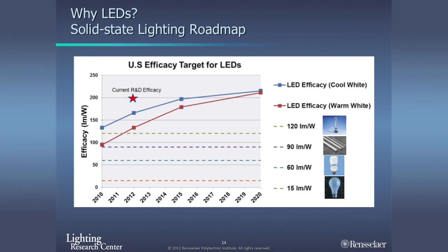They are typically more efficient because they rely more on the LED and less on the phosphor. So those are up almost to 200 lumens per watt by now, and then we see the warm whites a little bit under that, about 160 to 180 lumens per watt. But still, from an efficacy standpoint, that's much better than existing sources. By 2016 or so, we will see them cross the 200 lumens per watt mark, which makes it twice as efficient. So imagine that if you have fluorescent lighting in your building and you were to replace it all with the very highest quality LEDs, you could potentially cut the cost of that by 50%. And that's huge. Never before have we had a technology where we could really cut in half the energy use of our lighting. So that's really the interest in this, coupled with the life.